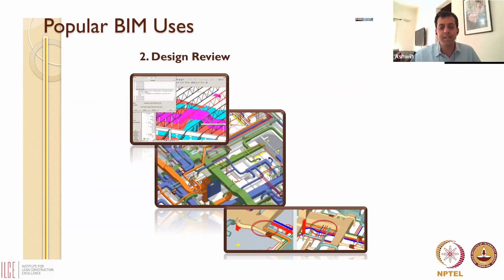Second, you have an issue that plagues construction sites called clash detection. Very often what happens is you have civil components, structural components, and mechanical and electrical components. When the mechanical subcontractor is trying to erect a duct on site, suddenly they might find that there is actually a beam that is blocking where the duct is supposed to be. Now, this means you have to go back and resolve how to reroute the duct. It takes time, and it costs a little bit of money.